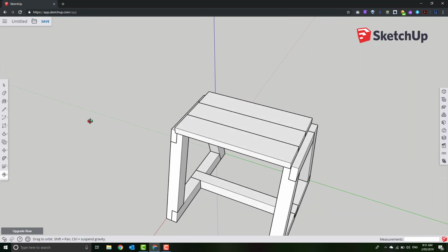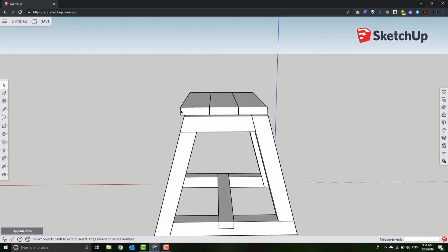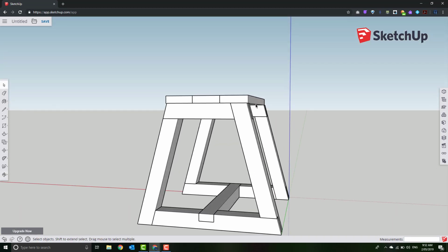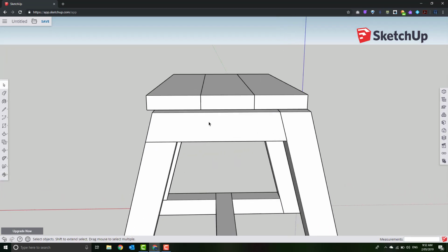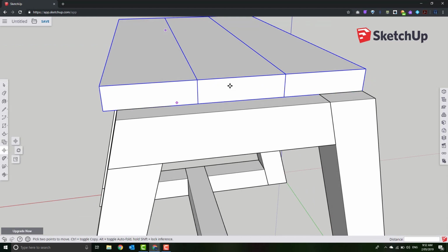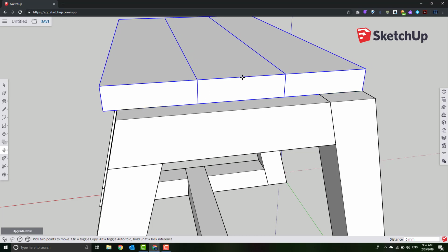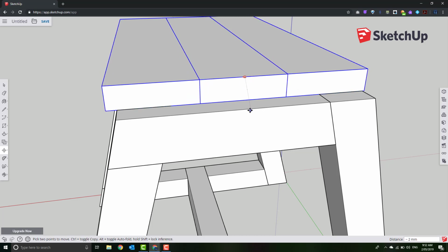Now I've got the 3 pieces that are the seat, and they'll be cut off on the same angle, so you can see that one's fine. Now I could work out and change my distance, but what I would do in the workshop is have 3 at 70. I've selected them all. I'm going to move from the center of that one, hold down Shift to keep it aligned, and then find the center here.